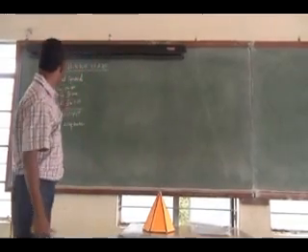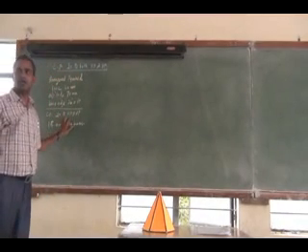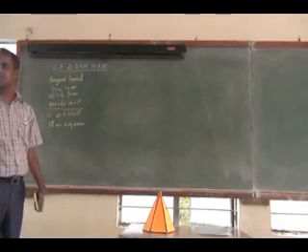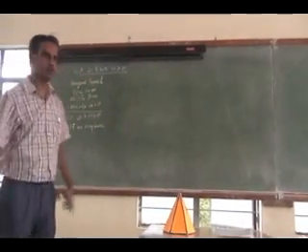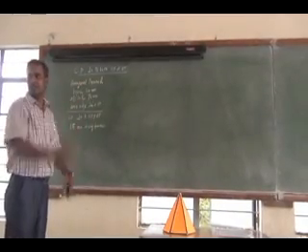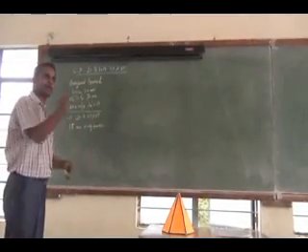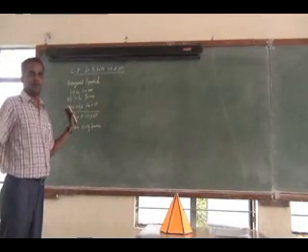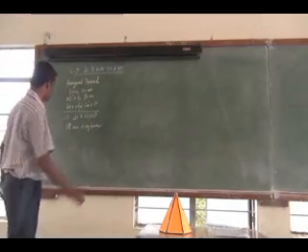So here, the cutting plane is perpendicular to both HP and VP. So the sectional side view itself will hold the true shape of section. Right. So you are asked to draw the front view, top view, and sectional side view. It can be the right side view or left side view. It is not mentioned. Any one view you can draw.